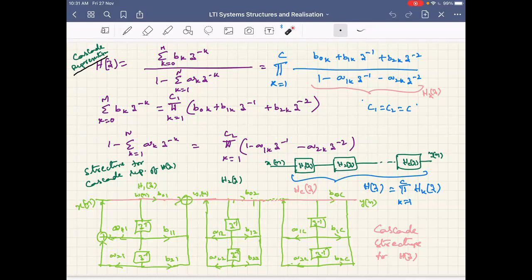Four. Yes, if the input is complex, then four are needed. But if the input signal is real, then you need only two multiplications. At least you need two real multiplications for each complex multiplication, whereas a real multiplication means only one. So that's why there is a multiply advantage if you can bring out the coefficients to be real rather than complex.